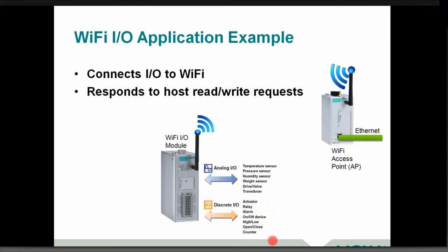Here's all of your on-off status, whether that be proximity sensors, level sensors, or limit switches. All of those are going to be your on-off status. If you're looking at time varying signals or analog signals, is it a temperature? Is it a pressure? Is it a humidity? Is it a weight that's coming in? Maybe you want to control the speed of a variable speed drive, and that's done through a 0 to 10 volt signal as an output. Here's where those come in.